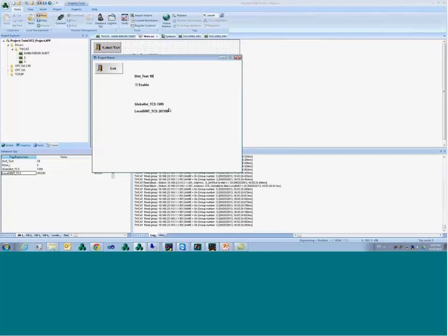All right, so as you can see, it's not that difficult to configure. If you have tag structures, you can put them on Web Studio. If you have nested classes, all types of things, arrays, they are all compatible. Whatever syntax you use on TwinCAT, you use the same syntax on Web Studio, and that's going to communicate.